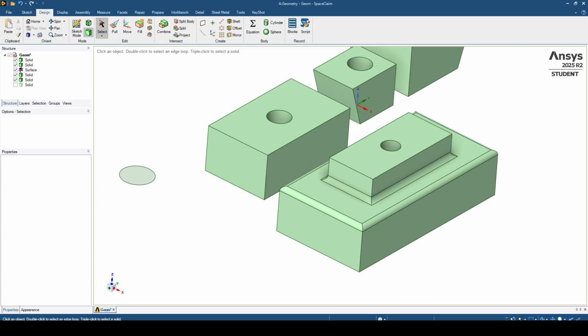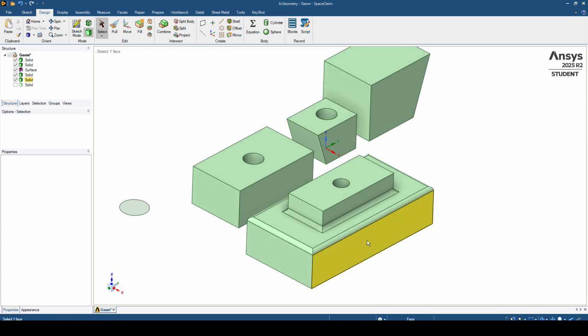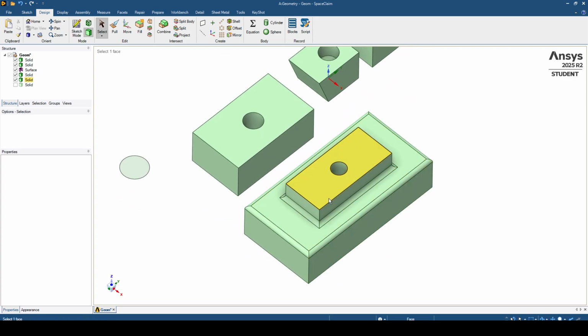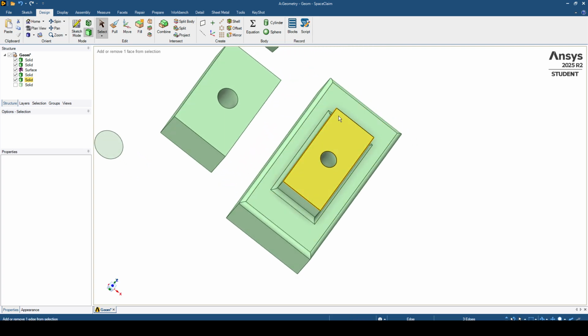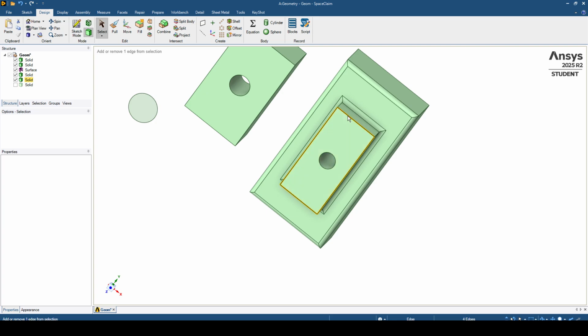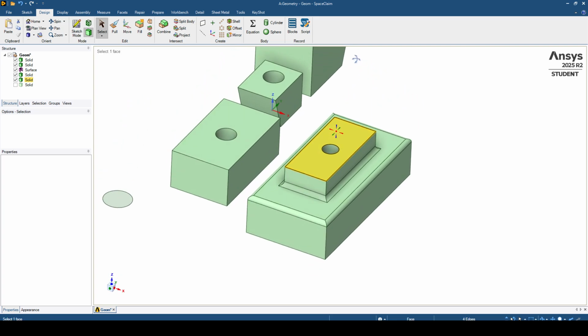Now let's look at the chamfer tool. Chamfer is similar to fillet, but instead of creating a rounded edge, it creates a straight angled edge. Select an edge, then activate the chamfer tool. How to do that? We can use the same strategy. We will click on these four edges, for example, at this location and this location. Now we clicked all four edges.